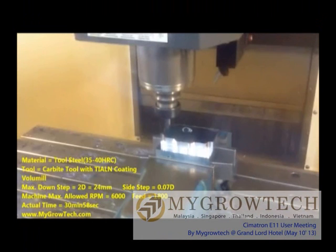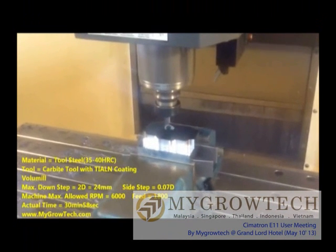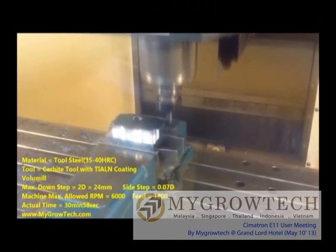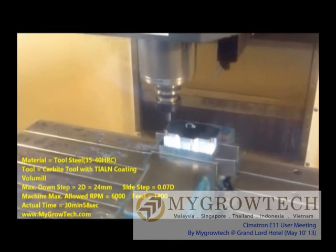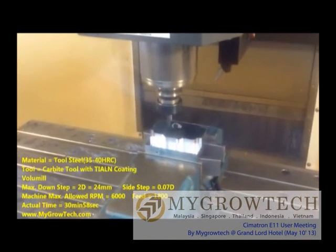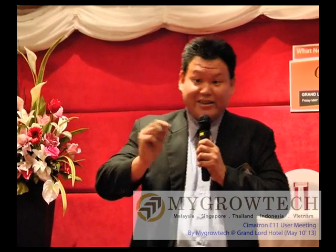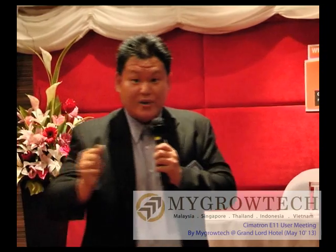Yeah. Because this is a 3D part. If I use a downstep of 24 mm, you will have a big step remain. Okay. Currently, the software will automatically clean up the step to make it smaller. Okay. And this is automatic part of the residue. Yeah, for 3D.